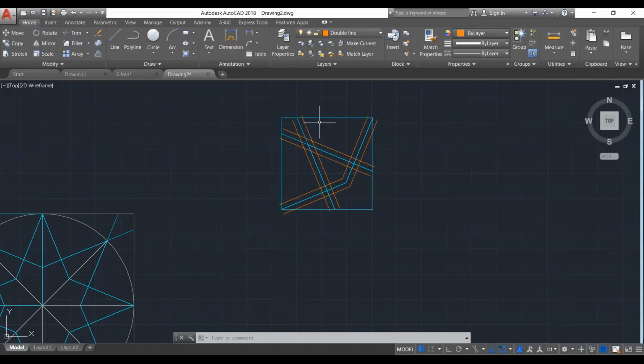First of all, you will see that all the lines drawn as multi-line are blocks. See here, this is one block, this is a block, this is a block. Don't explode them before finalizing all the options you need, and we will see what options we still need.